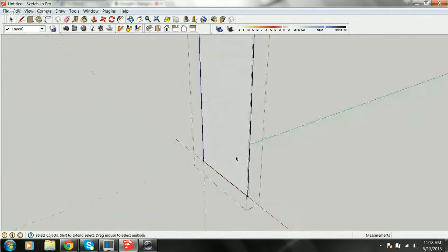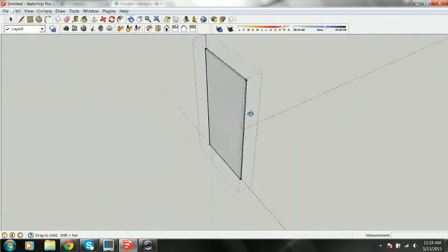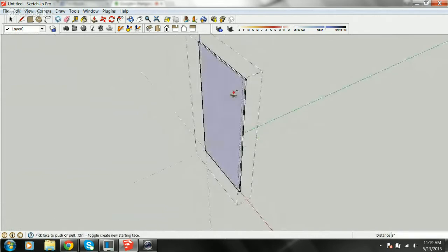So one of the things I just try and remember is hit that control button after you hit push pull. For the way I use SketchUp, that makes it remember that it's a solid. So as you get into adding and pushing and pulling more details, you're pushing and pulling things through a solid. But that's just a tip that I've learned through modeling and having some problems with some renderings. Perfect. For Shapeways, it becomes critical because Shapeways wants to read a solid. Okay, so 3 inches is where we're at.